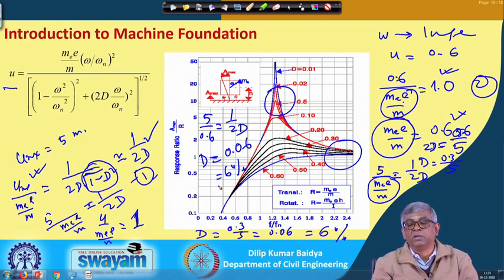So, I do not know any machine details, what is the eccentric mass, what is the speed, and what is the total vibrating mass, nothing else is known. But by increasing the frequency we have observed the resonance. At that point the amplitude is noted, and the frequency is increased significantly, and when the amplitude becomes constant, that amplitude is noted.